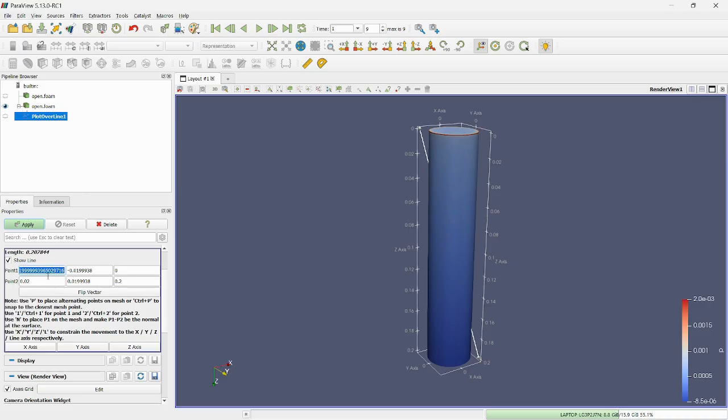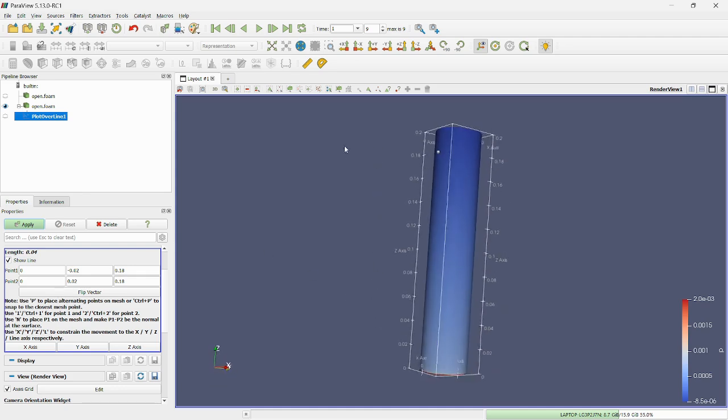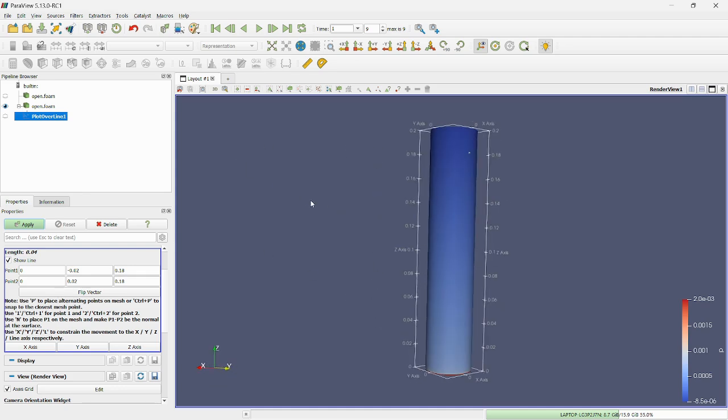We'll choose the y direction, so we're going to hold x to 0, and we'll vary the y across the radius, or diameter, I guess. And we'll pick a point pretty far up the pipe. Depends on your entrance length, but we'll do 0.18. So our whole pipe is 0.2 meters, so 0.18 is like 90% of the way up, I think, if my math is correct.